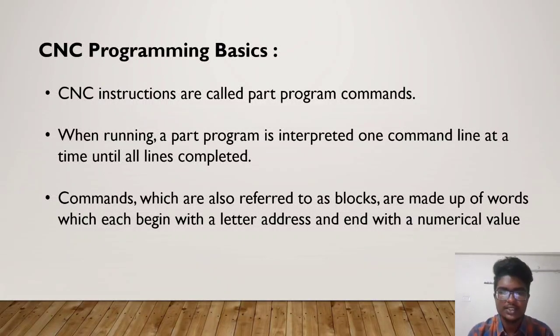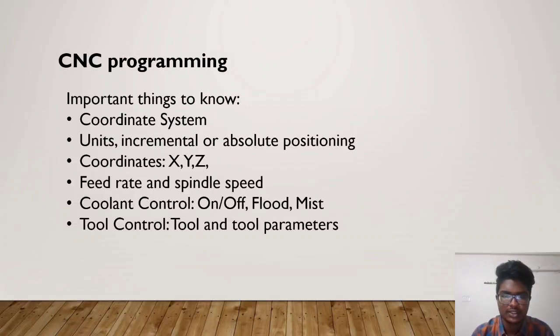So CNC program basics. In a CNC machine, the basic need is to know CNC program basics. Only when you know how to write a code can you use the CNC lathe machine. CNC instructions are called part program commands. When running, a part program is interpreted one command line at a time until all lines are completed. Commands, which are also referred to as blocks, are made up of words which each begin with a letter address and end with a numerical value. What is a letter address? It's going to be seen in the next slide.